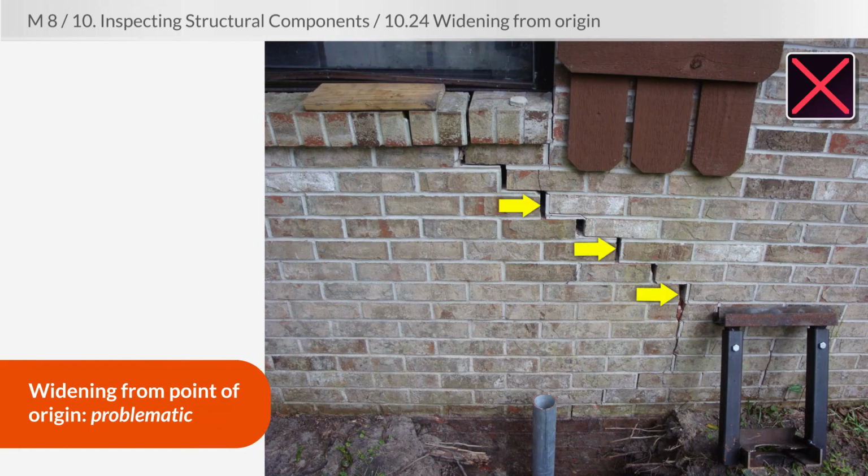This crack gets a lot wider as it moves up, to the point where you've got some pretty significant cracking right underneath the window. This type of cracking also will show up somewhere else in the house. Whether it's around the corner or in a longer ranch-style home, it might even show up on the other side of the house.